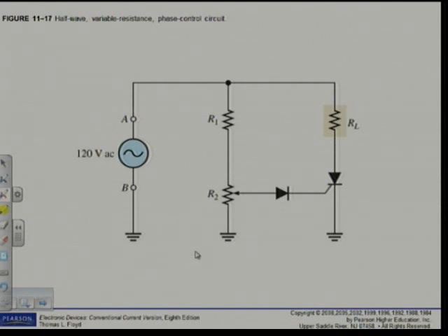Why did we talk about half wave? Because you will notice we got only one SCR in the circuit. Now we know a SCR or a diode got the capability that current is flowing only in one direction. That means if I think about my input wave, that means only half of the power will be available. During my positive cycle, when it's positive here, negative there, the diode, the SCR can conduct. For the negative cycle, when it turns around, when it becomes negative positive, that SCR will be reverse biased and we won't be able to get any flow.